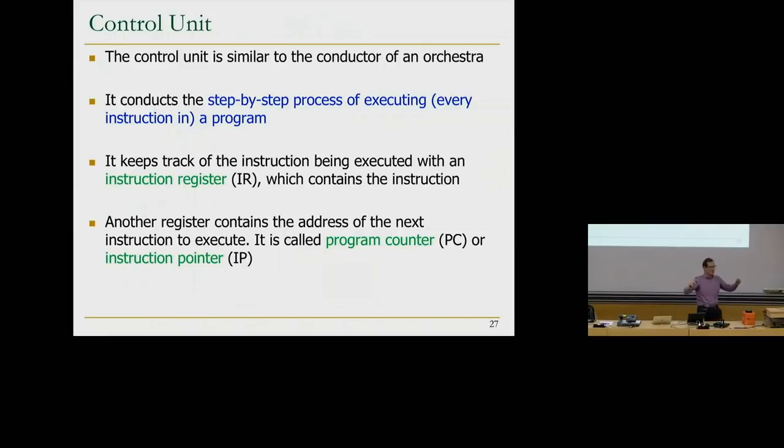So the first thing that happens in a machine is the machine gets loaded with an instruction pointer that points to the beginning of the program. Okay? And there's circuitry in the machine that we will see that goes and loads the instruction, the word, 32 bits in MIPS, 16 bits in LC3, into the instruction register.